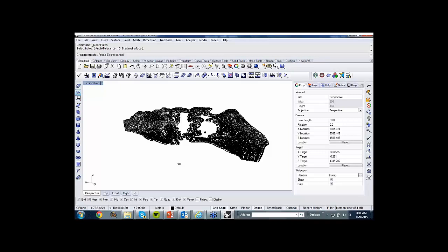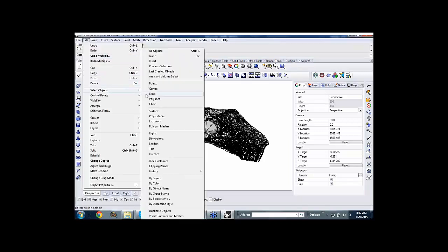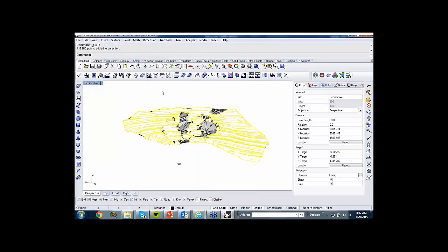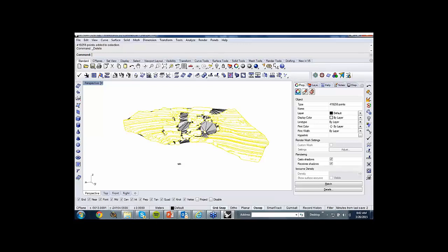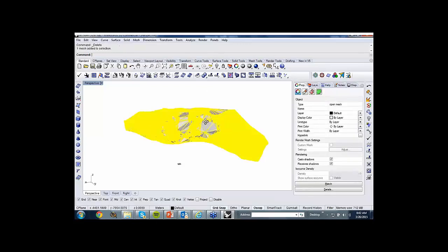So I'm going to throw away all the points that I have because those points take a lot of energy from the computer. So I'm going to take it out. So delete those curves. So what I have is this surface. It basically used a very intuitive approach of connecting every point to its neighbors to create a triangle. That is essentially what is called the Delaunay triangulation, a very natural, metric-based way of creating triangles.